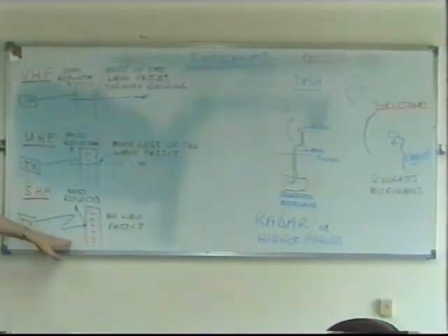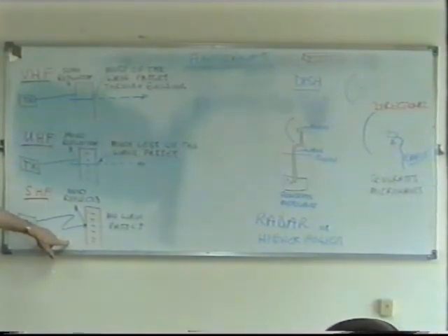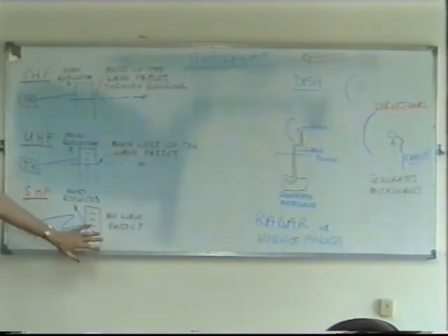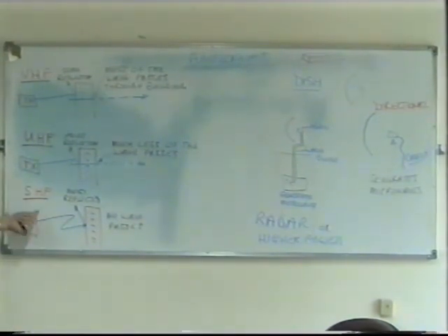SHF, forget it. You're not going to use it. This is no good at all to go through buildings. Okay for point-to-point microwave, but useless for mobile communications. Just don't even consider it, even though there's plenty of room in the band, but that's no good to us. And that's really the lesson of what we need to remember here about which frequencies are going to be used for what.